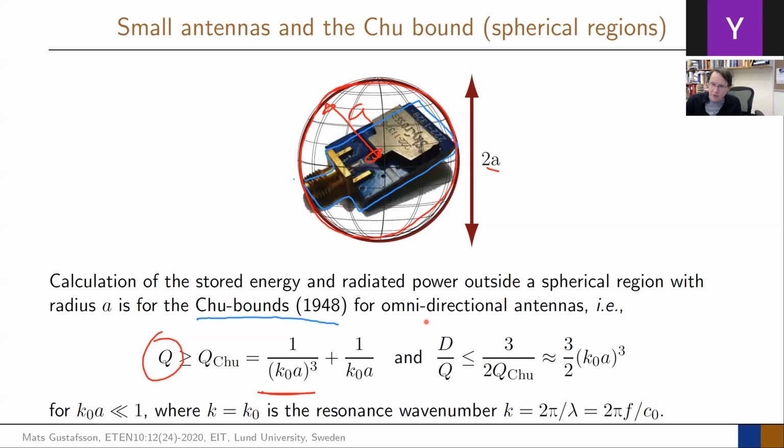What it means purely physically is that this Q factor measures how much energy is pumping around your structure. It's a reactive energy pumping like this. It doesn't just radiate out. And the smaller you make it compared to the wavelength, the more the field has this behavior. If you make it large, it behaves more like just radiating out. But this is a pumping field forward and back. And that pumping electromagnetic field will dominate everything that's happening with the antenna. And that is the price we pay when we make it smaller. We get larger reactive components, that pump forward and back.